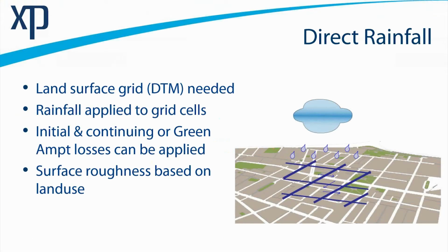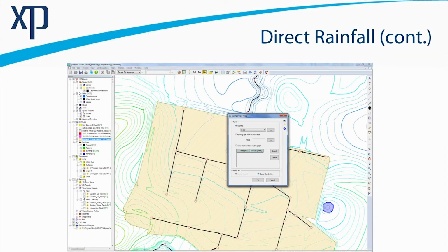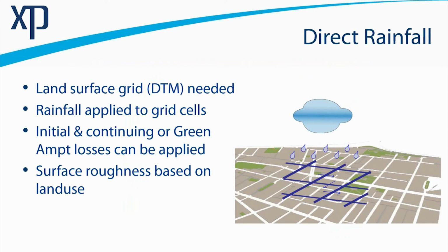What is becoming really popular in certain parts of the world is this concept of direct rainfall, and that concept relies on a 2D model rather than a point 1D model like that simple one node that I showed a second ago. It means we need to have good surface information, and unfortunately I'm aware that surface data is at times limited in the Malaysian region, but over time no doubt the capture of completion of aerial survey, obtaining LiDAR information will improve and be expanded.